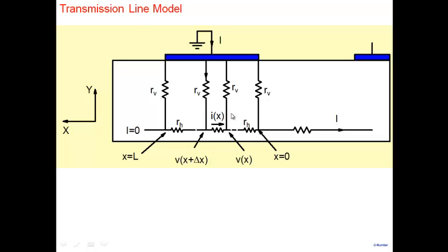It may not be as neat as that. But this is a model that is often used, the transmission line model, which captures that there is a contribution to the contact resistance coming from the contact resistivity, and there is a part which comes about because of the flow through the N-type semiconductor also. So we are modeling it in terms of a resistive transmission line here.